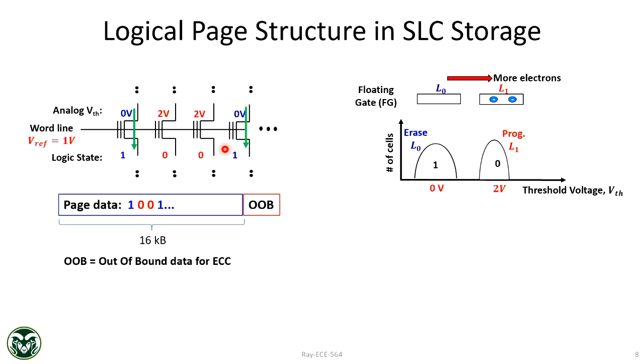For multi or triple level cell, is it a matter of time the voltage is applied? Yes, this time will also be higher, and also you have to do it precisely. So that's program and verify. Verification will be done. In this class, I'll go to that level. At the end of the class, I'll show how exactly multi-level cells are programmed. But I hope the SLC logical page structure makes sense.